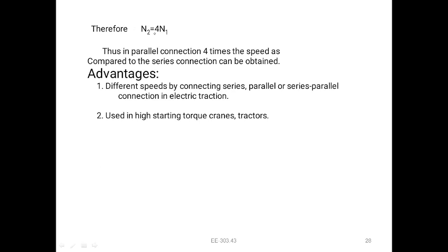So here, therefore, N2 is equal to 4 N1. Thus, in the parallel connection, 4 times the speed as compared to the series connection can be obtained. So we can get more speed by connecting in parallel compared to the series.